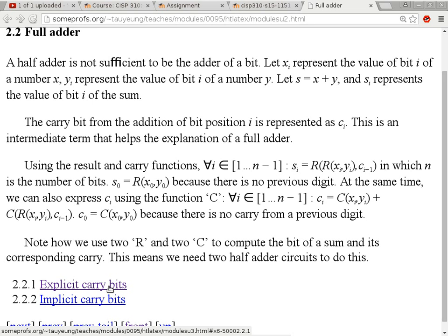How would it know, how does it determine the time needed in order to say it's safe to use that answer? Experimentally, empirically. What Intel or AMD would do is they would characterize their transistors, and basically try to change the clock speed until they get past the reliable point, and then they back up a little bit.